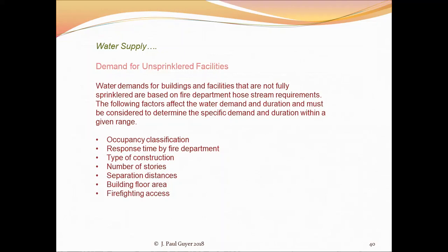The occupancy classification, response time by the fire department, because the fire department is the only method that you've got available, absent a fire sprinkler system, to put out the fire. The type of construction, is your building made out of wood, concrete, steel? Number of stories, separation distance to other buildings, and building floor area, and then firefighting access.